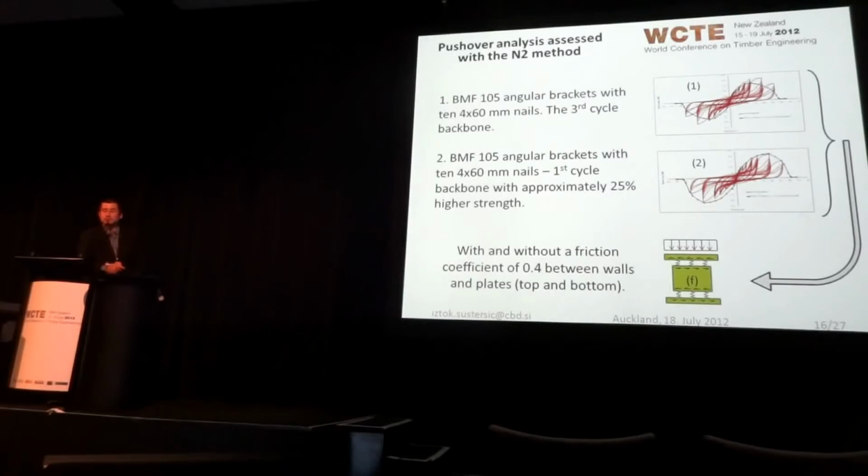And if I move to the second to last chapter, the nonlinear dynamic analysis, we were strictly following the Eurocode 8 procedure, so the accelerograms here are just based on the Eurocode strong motion database, scaled. They were not correlated to fit the spectrum better, so they came as they came. We were using the Rexel software to pick them out. We were also using SAP to model nonlinear time history analysis, so the hysteresis behavior is not perfect, but it's sort of there.